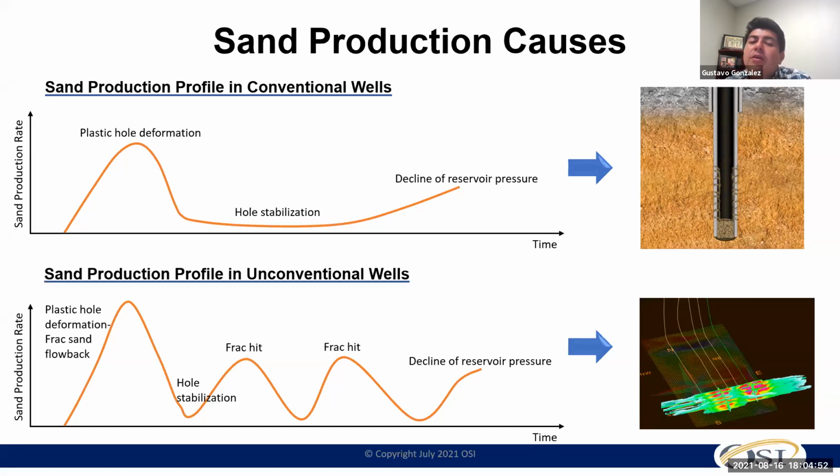If you don't have enough bottom hole pressure, what you have to do is take a decision to go with an ESP or gas lift and set your artificial lift system to handle the sand and be able to produce the sand, because your bottom hole pressure was not enough. But we're going to get that peak. We try to see some stabilization, but based on the areas, we have